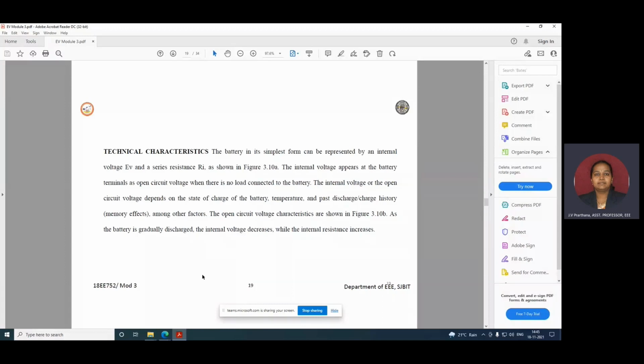Battery temperature, heating and cooling needs. Although most batteries run at ambient temperature, some run at higher temperature and need heating to start them. So this basically decides the efficiency. When choosing the batteries, the designer needs to be aware of the battery temperature, heating and cooling needs, and has to take that into consideration during the vehicle design process.